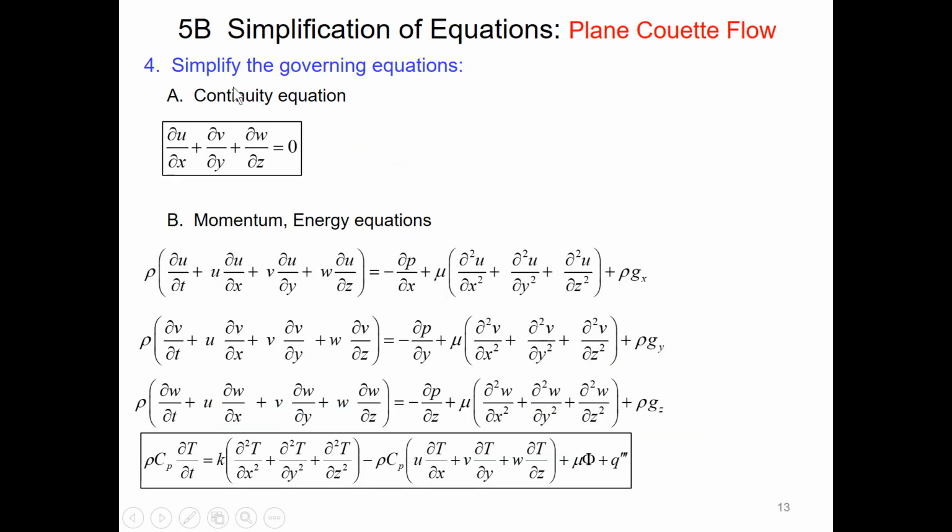4. Now we will simplify the governing equations: continuity, 3 momentum equations, and 1 energy equation. A. Flow is steady, so all the derivative terms with time are gone.